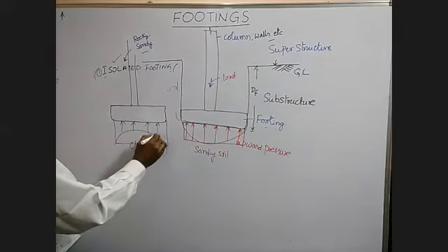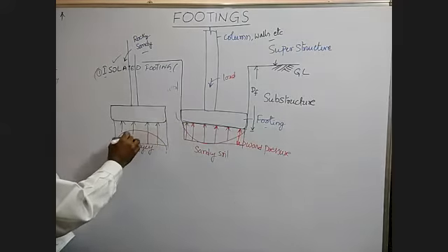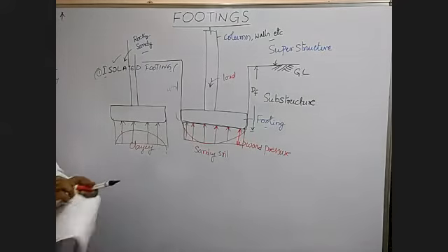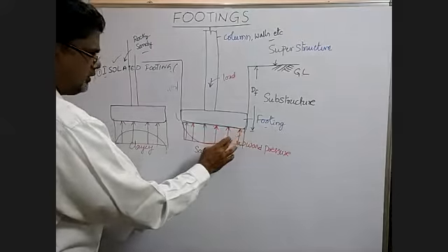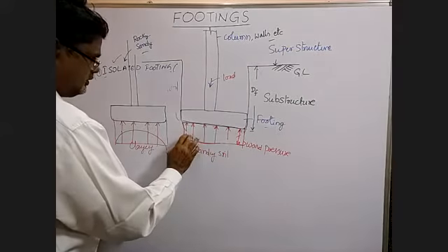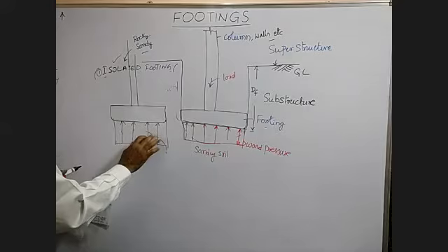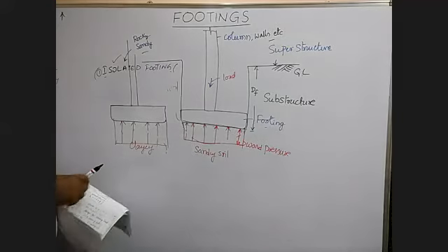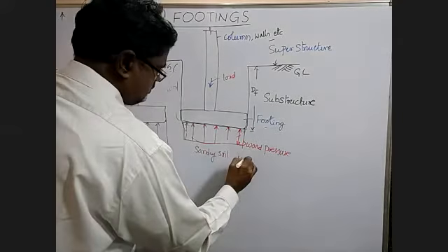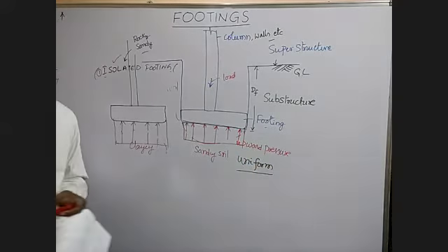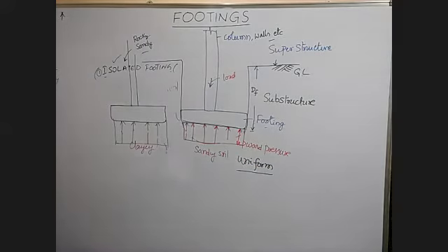For the design of the footing, even though for clay and sand the pressure diagrams are different, we assume for design purpose that the pressure is uniform. Okay. So this is regarding the soil pressure.